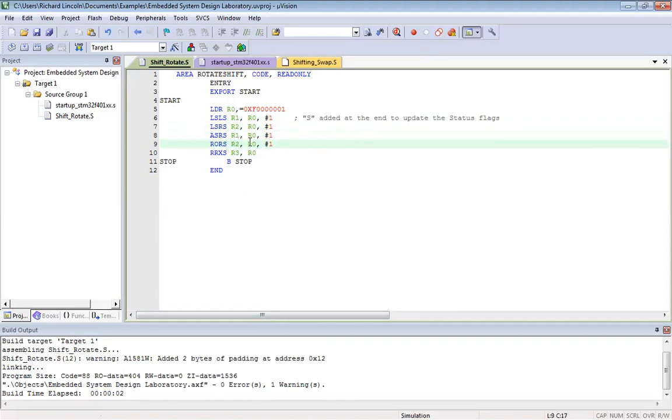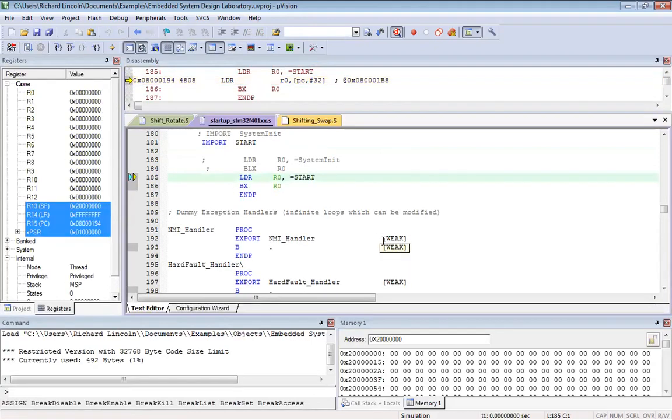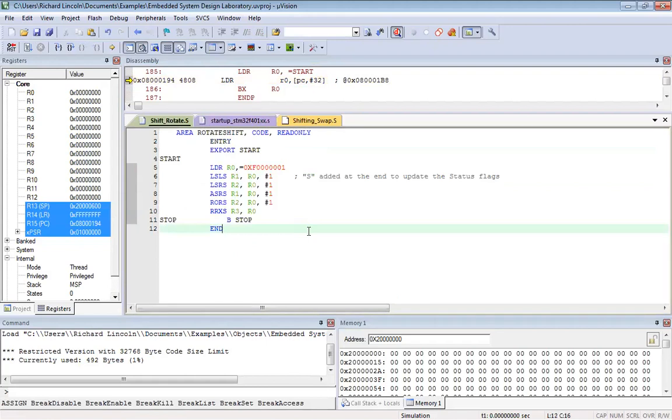Now I'm going to rotate the value. Same thing, I'm taking only the R0 value, and these operations are done. Once I do a rotate on the R0 value, I store the result in R2, right? Extended right rotate is going to be with R0, and destination is going to be R3. So you can put these values bitwise, like how I had put them in rectangular boxes, and you can try and execute them, right?